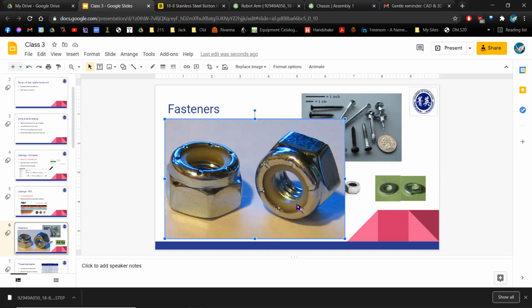And what this prevents is sometimes when you have a part that's moving around a lot, there's vibrations, and those vibrations can over time unscrew your nut. And what this piece of rubber does is it reduces that impact and makes sure it doesn't loosen over time. Because that's actually a big problem with these parts.